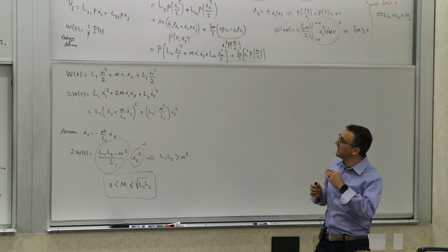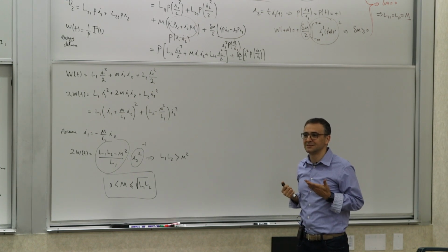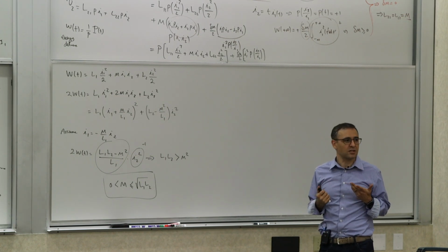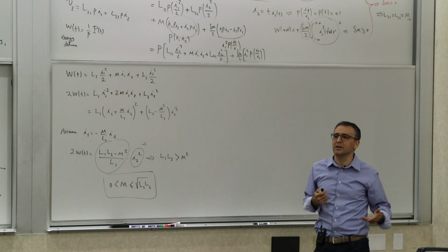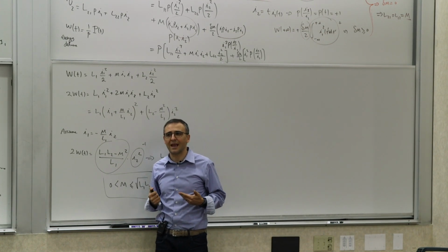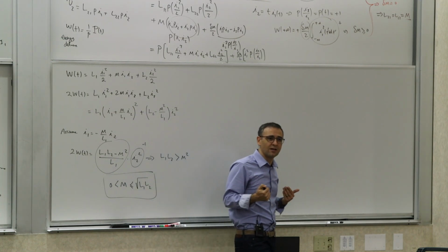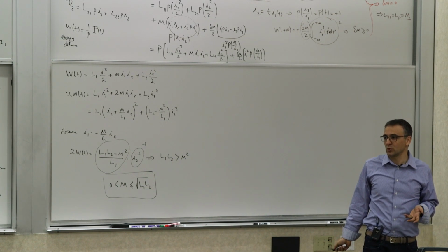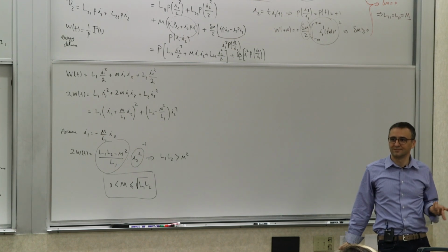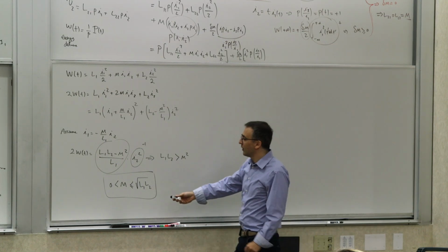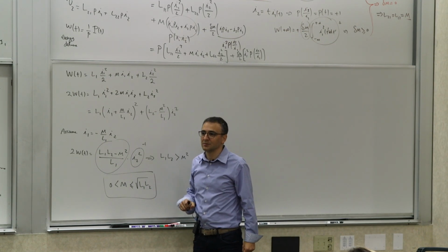It means that you can't pick any arbitrary value of m. So if your primary inductance is 2 Henries and your secondary inductance is 8 Henries, m cannot exceed 4 Henries, the square root of 2 times 8. This is important, otherwise your element is not passive anymore.